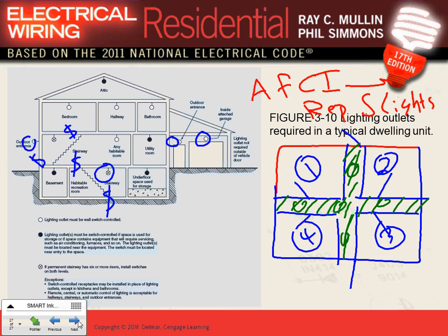It watches and monitors the signature of this arc, and it will trip. It has an electronic circuit that analyzes that little signal that looks weird, and it will trip the circuit breaker upon the existence of the arc, because they discovered, people smarter than Chad, that a lot of fires are blamed on, rightfully or not rightfully sometimes, electrical arcs.